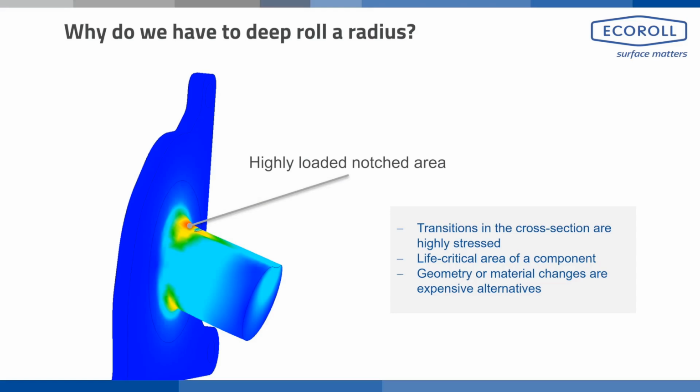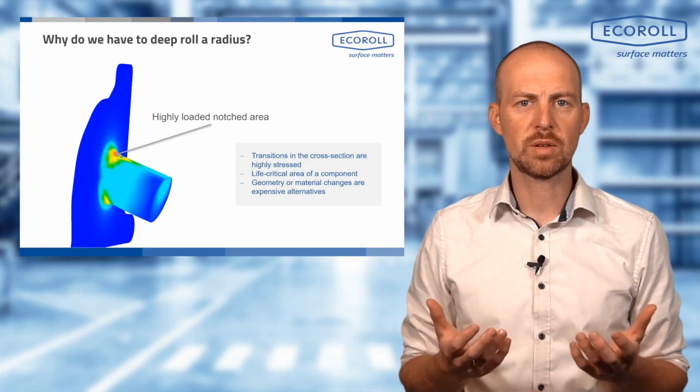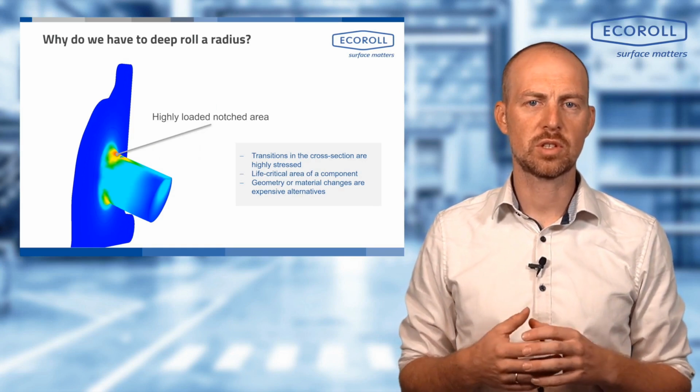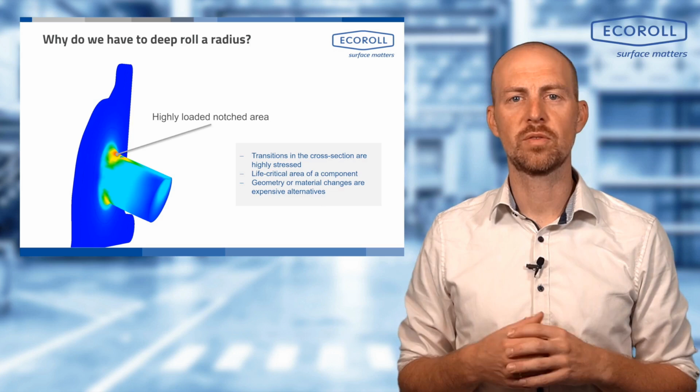Curved arches and radii are important elements of mechanical engineering. They are always used where shaft steps occur and where one diameter follows another. This is exactly where the highest stresses occur under load. Here we have stress peaks that cause the material to yield at this point. This means that a shaft will always break at the transition of the radii.